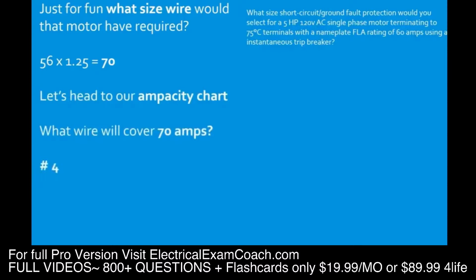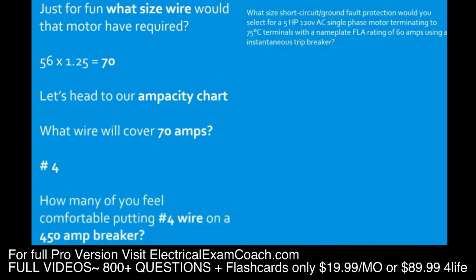So legally, in this situation, you could put number 4 wire on a 450 amp breaker. Okay, now that would be the original breaker that you did back at the original panel. You would still have overload protection, but still, it's just outrageous to think that you could put number 4 wire on a 450 amp breaker.